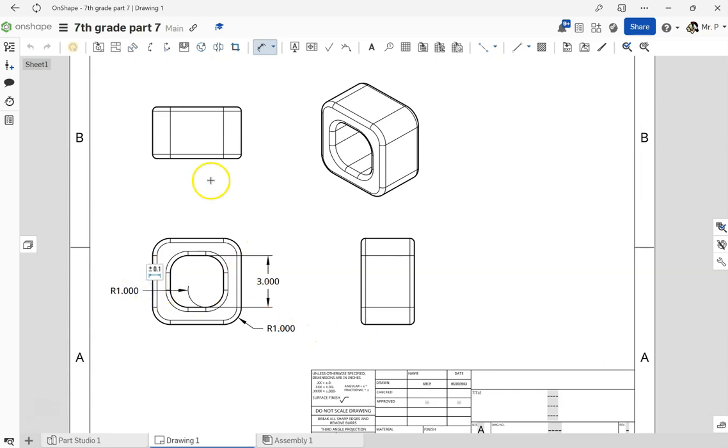In this case, with these fillets applied, I can't just click this short line here. Sometimes I can. I will say, please don't do that because it will create some errors for you. So click between this arrow to this arrow is going to be 5 inches, okay?